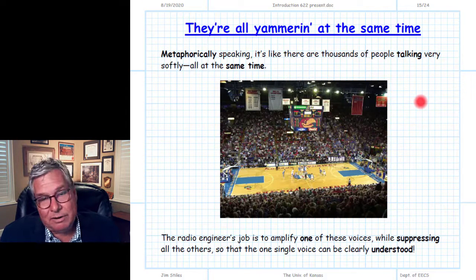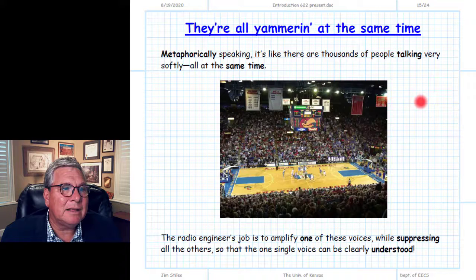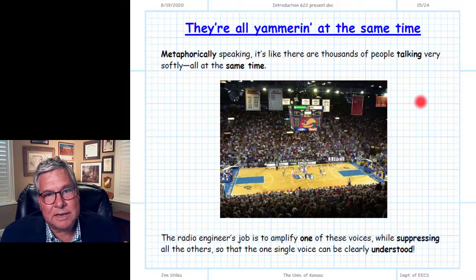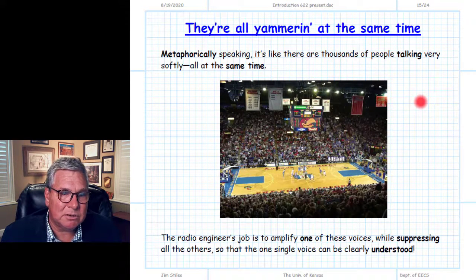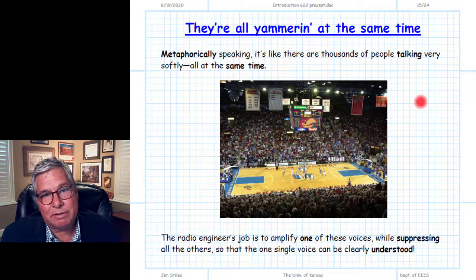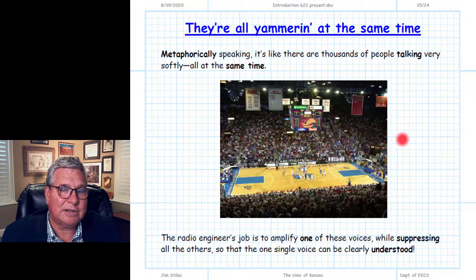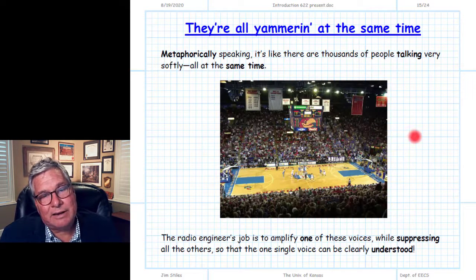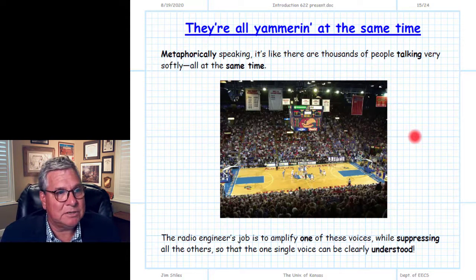And they all can theoretically make it to the input of your receiver, of your FM receiver, for example. And that receiver has to be able to reject all of them, save the one that you're interested in. So it's not just simply rejecting all the other FM radio stations. It's rejecting all the signals that are being radiated at any and all other frequencies except for 101.1 megahertz.